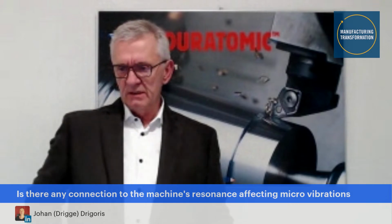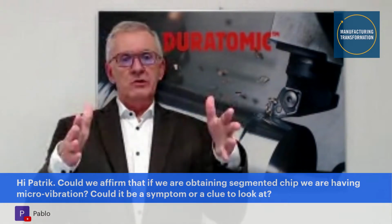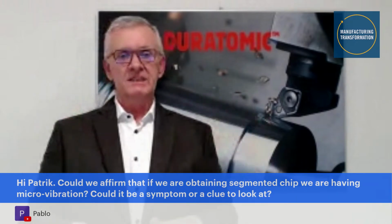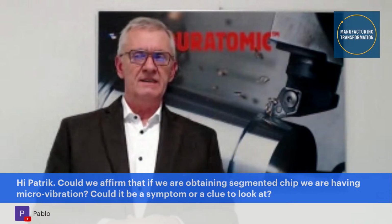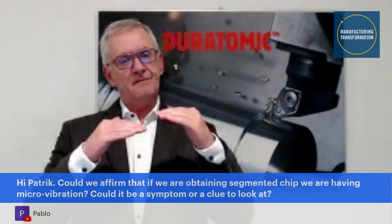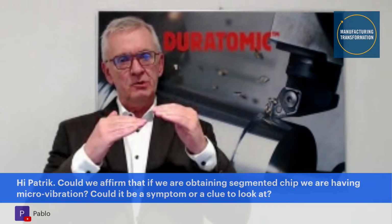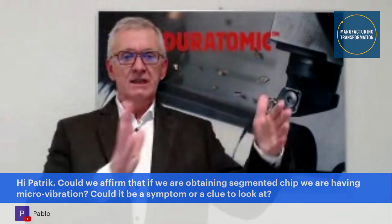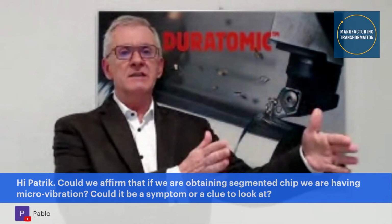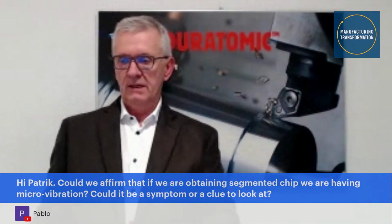The third question, could we affirm that if we are obtaining segmented chip, we are having micro vibrations? The more a chip is segmented, the higher the risk is there are micro vibrations. Of course, there are things like the stronger the cutting tool, the more I force a cutting tool in having during cutting a fixed cutting line position, the less risk for vibrations. But in the general thing is segmented chips, the higher the segmentation, the higher the risk for micro vibrations. That's the general rule.